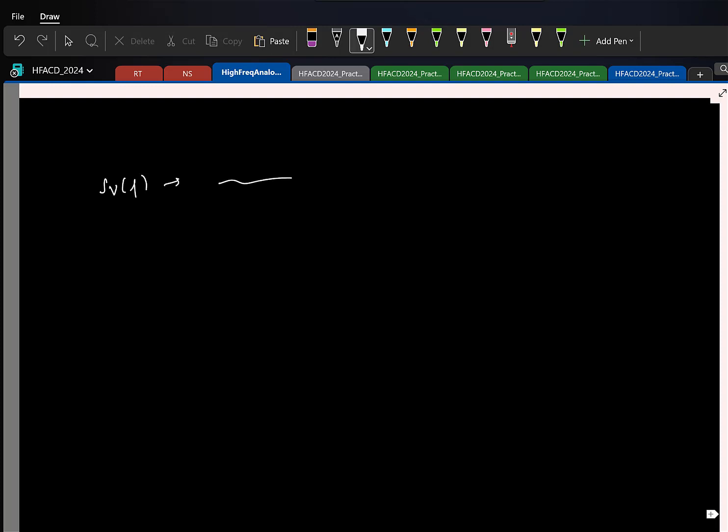That will set a limit on your gm1, right? Because as you know, this is going to be some 8kTγ by gm1 plus something. So you should design your gm1 based on this. As a designer, that's what you will do, right? You analyze, but the reason we are analyzing it is that you should be able to use the result for your design. So this is nice, you can do.